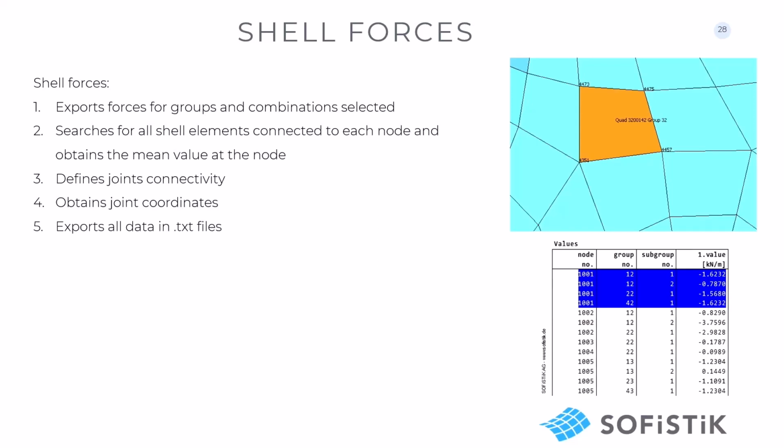What we work with? We work with shear forces because these elements are 2D elements. So they are elements, just to give you an idea, the typical CLT element is from 80 millimeter to, I think the maximum now they're producing is 340 millimeter thick. It comes in widths that range from 1 meter to, I think the maximum I reach now is 3.5 meter width.